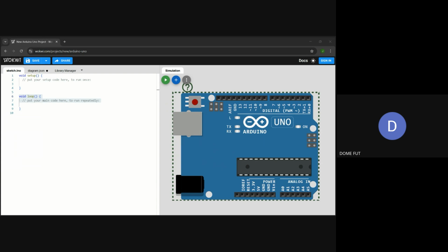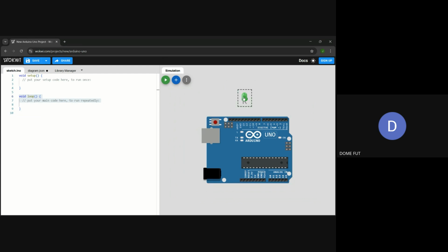Now, the positive terminal can be any other pin here. It can be 13, 12, any of these numbers depending on the type of device you are using. So one must go to any number and the other one must go to ground. Now, this LED is a digital device, because it can use a DC current to work. It's mostly a digital device. So what I can do is connect one terminal of the LED to ground, and connect the other terminal of the LED to maybe pin 12.